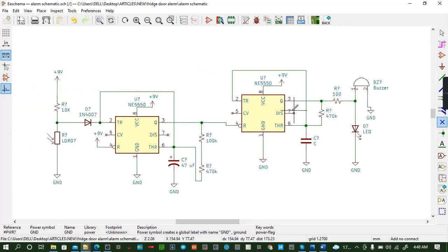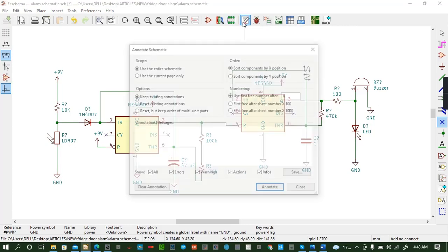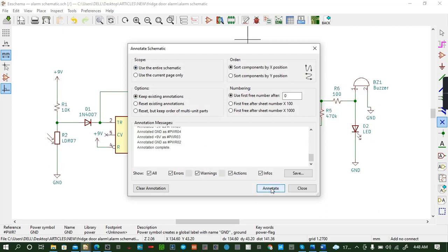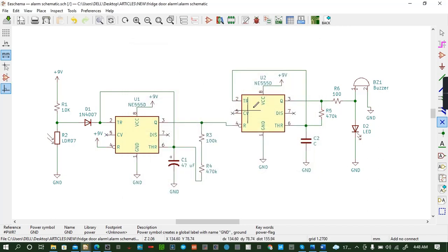But there are some pins that are not important, so you can close them like that, close them like that, close them like that. Then you can control save. So after placing our components, this is how our schematic will work. This is the sensor, and this is the board of the sensor. So you come to this bit whereby you have to annotate the schematic for it to have components. You see the components by question mark. So you can close it. Already it's annotated now. We have this one as U1, this one is U2.